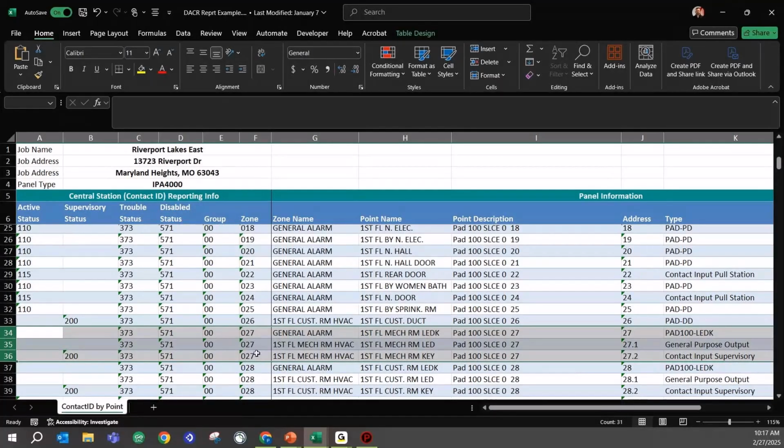Both of those inputs, now I realize in this case they're not both inputs, but both of these inputs are going to report to the central station at address number 27. So please keep in mind with those subpoints, if we're using something like a dual input module, if we have a water flow switch on input 1 and a tamper switch on input 2, that's going to be okay, because in that situation, it would show the top one, that's the module, that'd be a dual input module.